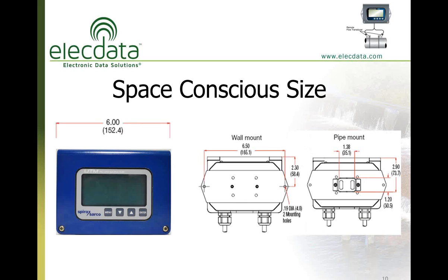As you can see, the UTM10 meter/display is very compact, 6 inches total width. It comes with a mounting bracket on the back of it that allows you to mount it directly to a vertical or horizontal pipe, or you can remove two screws that hold the pipe bracket on there, which just gives you a flat mounting bracket with 6.5-inch pre-drilled centers that allow you to mount it directly to a wall or to an enclosure.